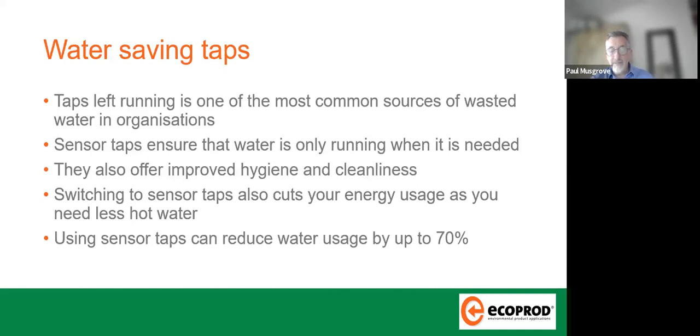Water saving taps. Okay. There are many electronic taps operated by sensors on the market these days. And unfortunately, many of us on this webinar today may have experienced inferior products that do not operate correctly, or possibly not at all. Selecting the correct product requires consideration of the environment, consideration of the users, consideration of the footfall demand 7 days a week, 365 days a year.